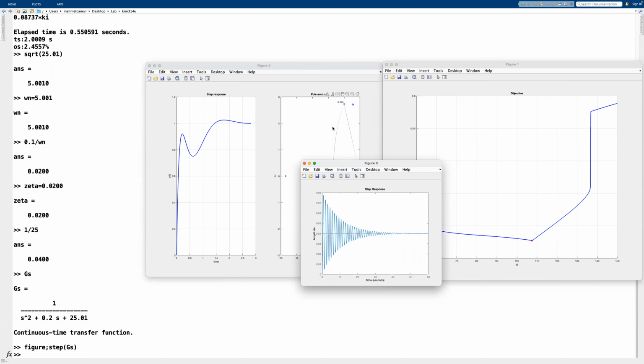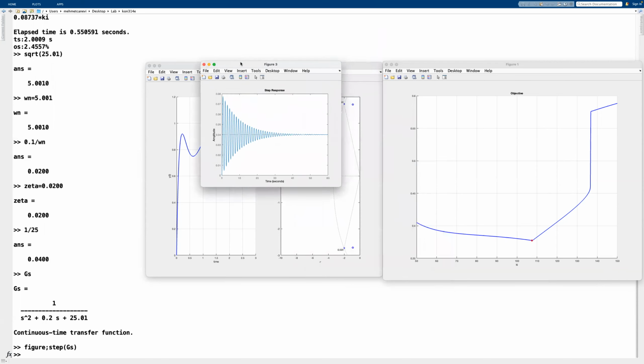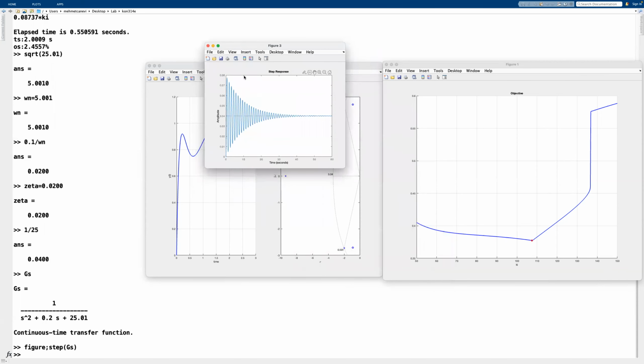Now, for this system, we're designing a controller. It is important to know what the open loop system looks like and how it behaves because, in this case, when we're trying to get rid of these pole pairs, we should be careful because we are somewhere along the j omega axis and we're near to it, because 0.02 is close to 0. So this zeta value here is not that big.